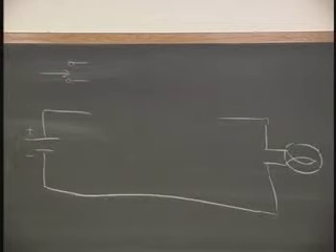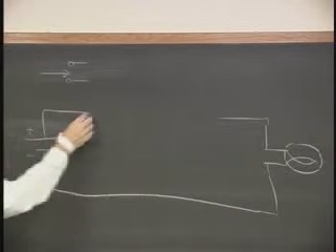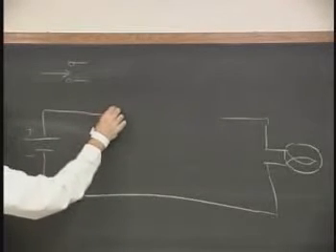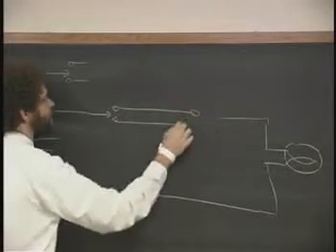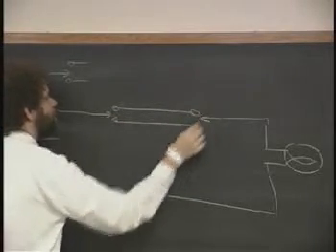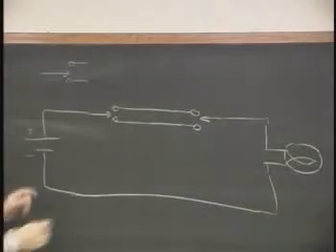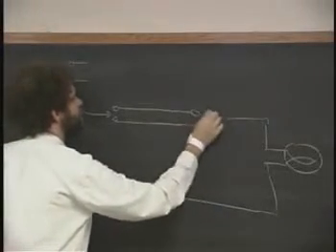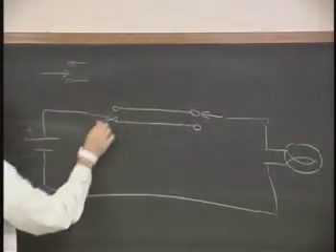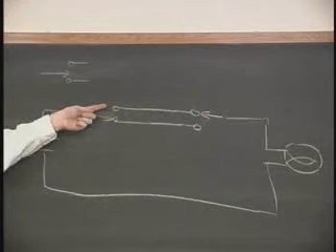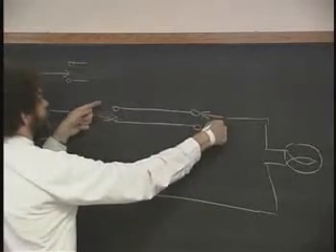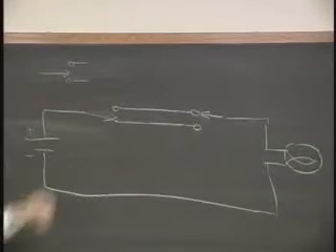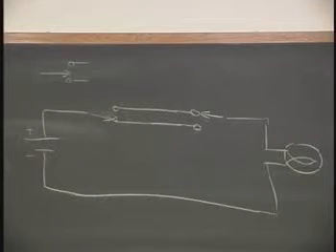Anybody want to take a guess? And there's a switch at the other end, pointed back. It actually doesn't matter if you cross the wires or not, but the switch at the other end is the right answer. It looks like that. So let's say this one is up and this one is down, then the light's off, but if you turn this one up, then the light goes on, right? But if you don't turn that one off, you turn this one on, then the light goes on. Whichever one you switch, the light will change from one thing to the other.